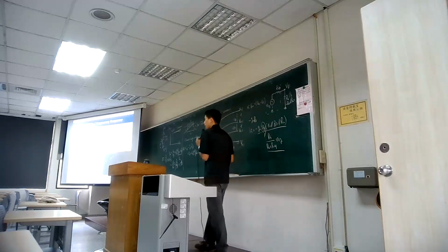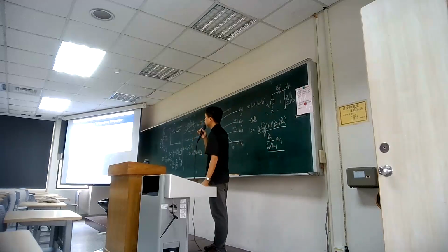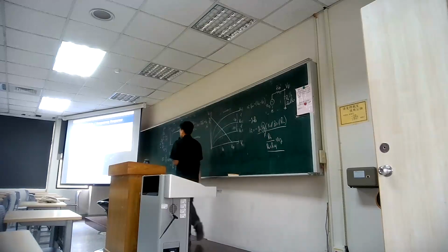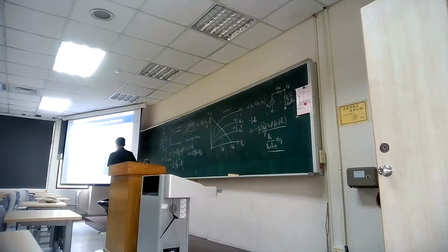Okay, so there will be an additional way to go. If you are interested, you can go back and look at the electronics textbook on the graduate level, to see what the application is. Here's one example. You can think that you have 1 millivolt as the input. What we get here is the frequency response. We get an output at around 2 millivolt. It means that maybe you double the amplitude, but not much. You will also notice there is a drop down or rollover at the low frequency. Please remember this one is not VDS over VD, it is the frequency over the output voltage. So why do we have this rollover?